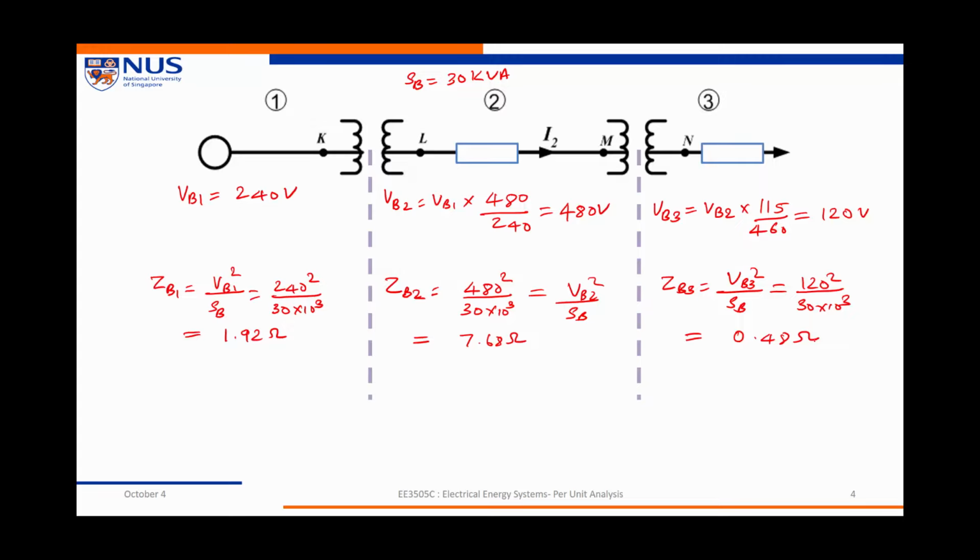Next, let's convert these values to the corresponding per unit values. I can say the V source per unit is equal to 220 at an angle 0 divided by 240, which is 0.9167 at an angle of 0 per unit.